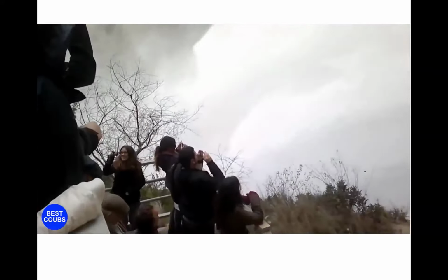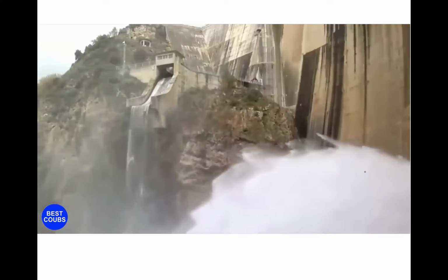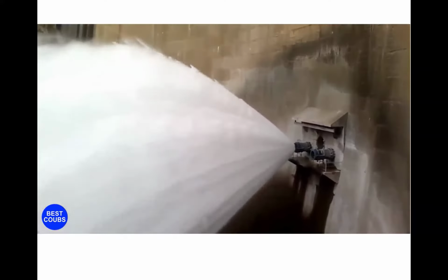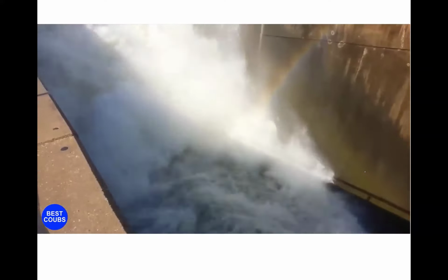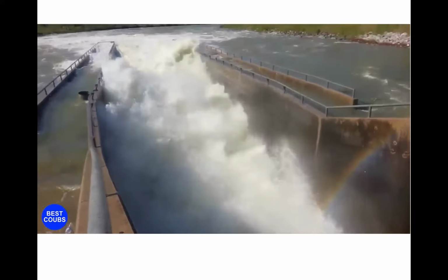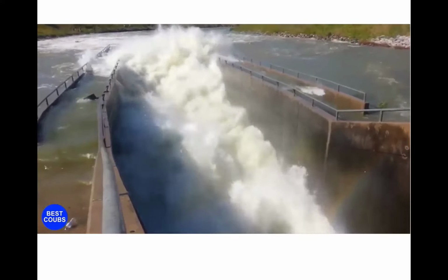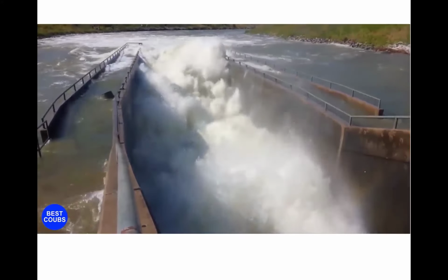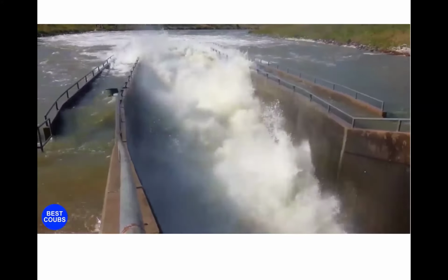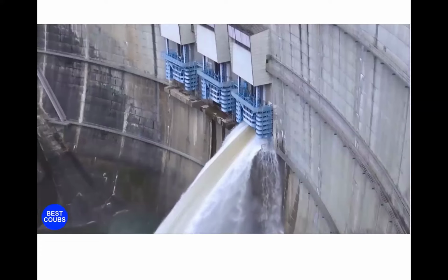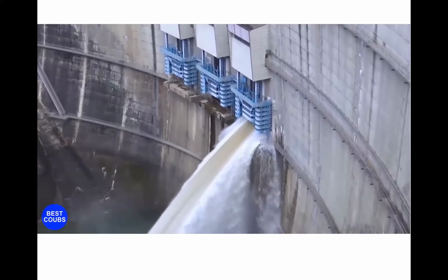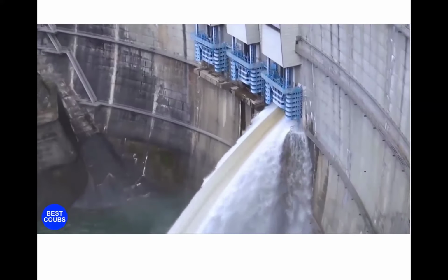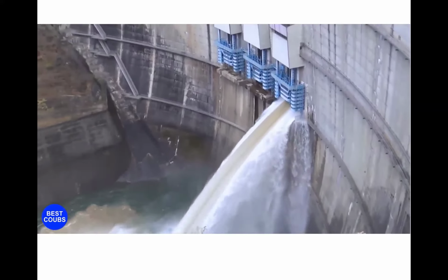This one's another outlet discharge, an orifice, really. The reason why the flow is splitting like that is because there's a valve inside. That's intentional, to break the jet into, again, smaller drops. This one's a very violent hydraulic jump. So what we're looking at was a hydraulic jump, but definitely not a stable one. Very, very violent and very turbulent.